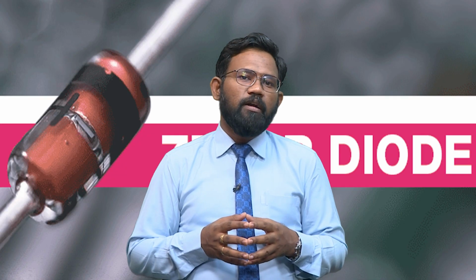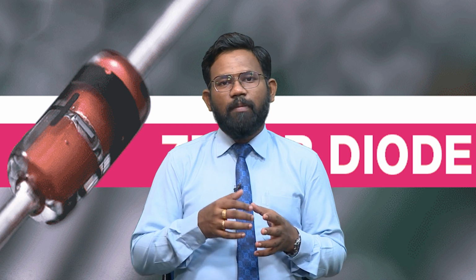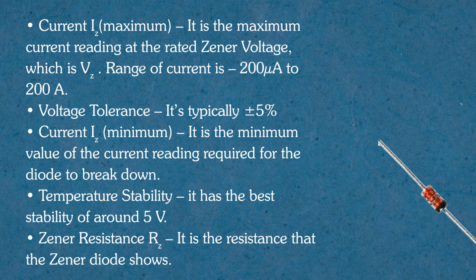The next rating is current, or the maximum current rating of the Zener diode. It is the maximum current rating at the rated Zener voltage, which is noted by Vz, the maximum Zener voltage. The range of current will be 200 microampere to 200 ampere. So this will be the maximum current rating for the Zener diode.